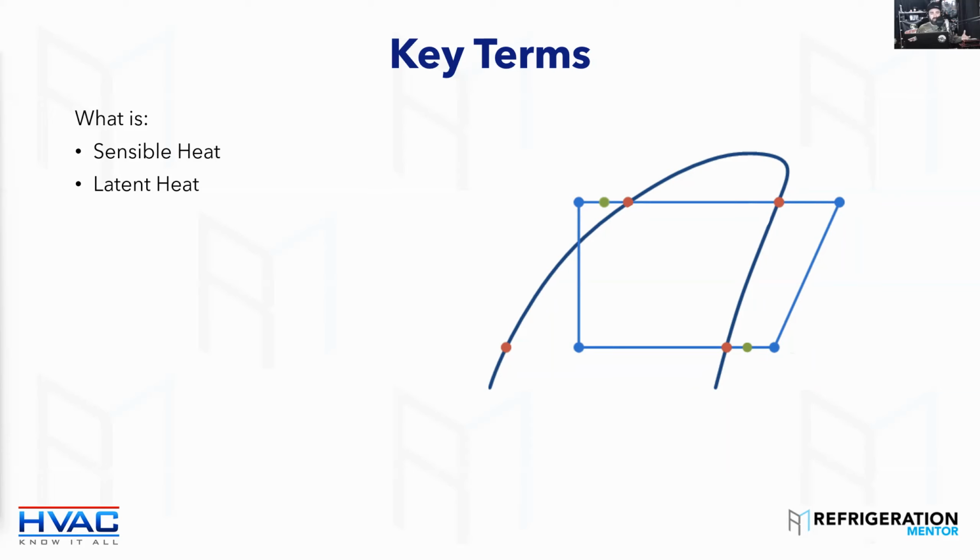Your AC is going to tackle that latent heat load, which is in the form of moisture. When we're removing latent heat, we're removing moisture from the air. Once it gets rid of that latent heat, then it's going to start tackling the sensible heat and dropping the reading you see on your thermostat. That's maybe a simple way to describe it.